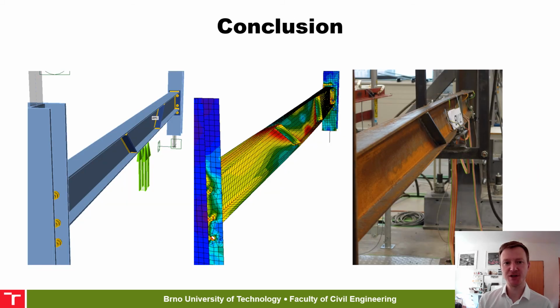To conclude, designing member together with joints brings advantages, but the traditional design methods are not ready for this. For example, lateral torsional resistance for semirigid joints is difficult to establish. The CBFEM model can be easily created and analyzed very fast. It shows the realistic behavior of both the member and the joints.